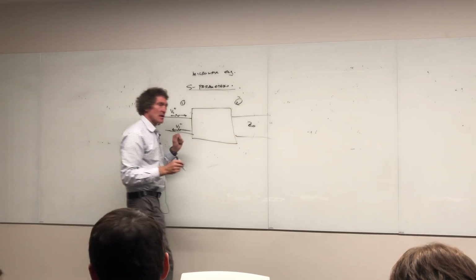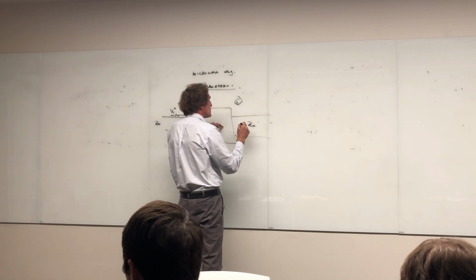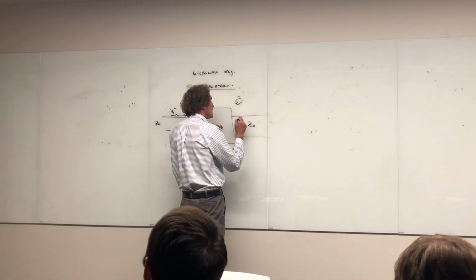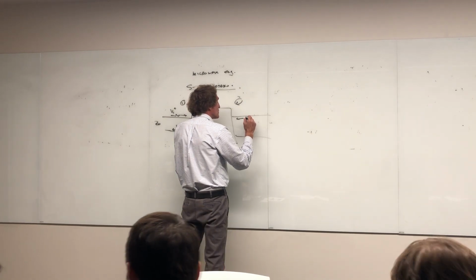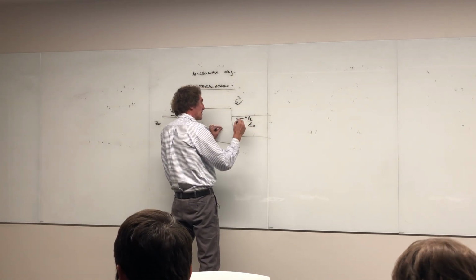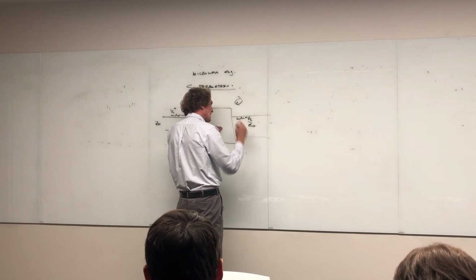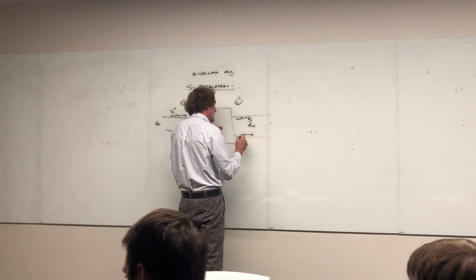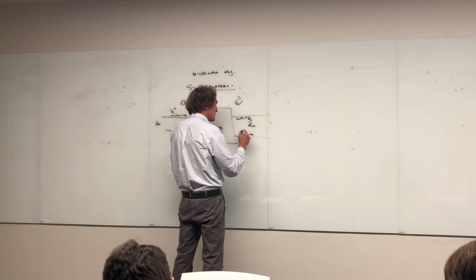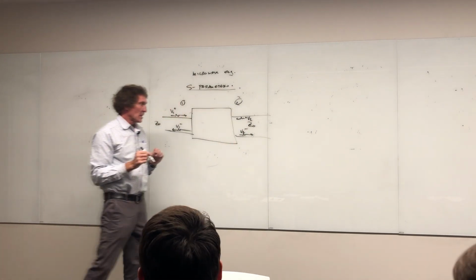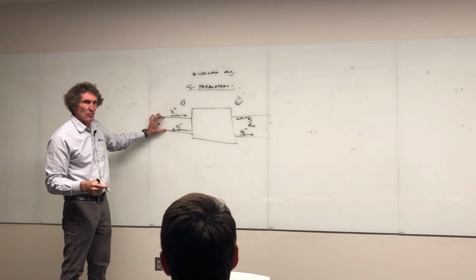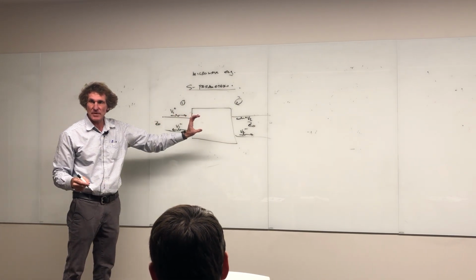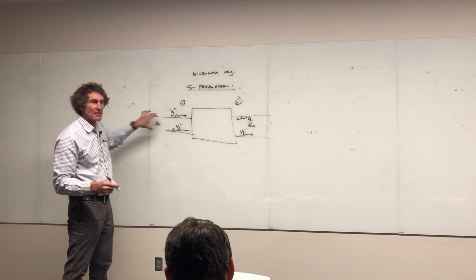Now over here, this is port 2. You're going to have a voltage moving this way that is called V2 plus. It's moving that way. And he always puts these squiggly lines to indicate it's a wave. And then we have something moving out. It's V2 minus. Now, remember, that voltage is developed from here to here. But one is a positive traveling wave in this direction. The other is a wave traveling in the negative direction, if you will.